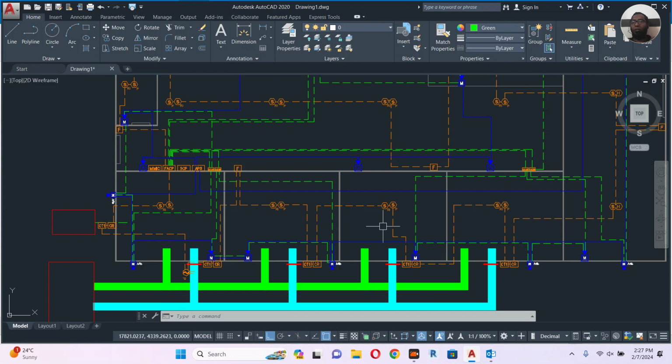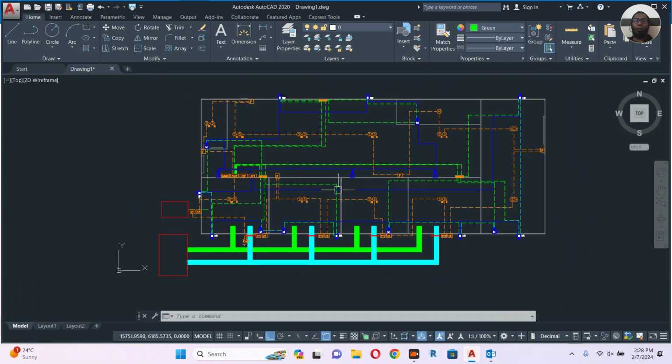So what we have to do is provide one control relay and sometimes a monitor module to monitor, and connect it to this certain point. Then the fire alarm control panel will understand and give a signal, and the fire alarm programmer will make a program for what should happen when the signal is received from the FACP through the control relay.